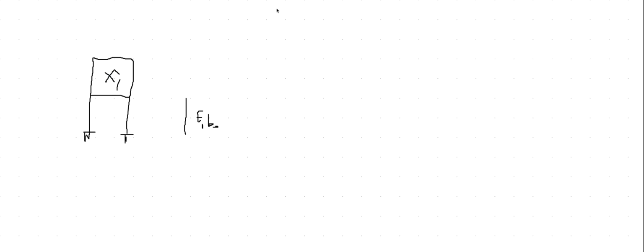So typically, you have here 2 displacements for each node, and you have this rotation. And then on top of this one, if I take, let's say, a single element to model this, I just have a typical membrane Q4 element, which has only 2 displacements. So what could happen basically if I do that? If I apply the forces here, this typical force here would be altogether F, right? So the sum of these forces will be F.